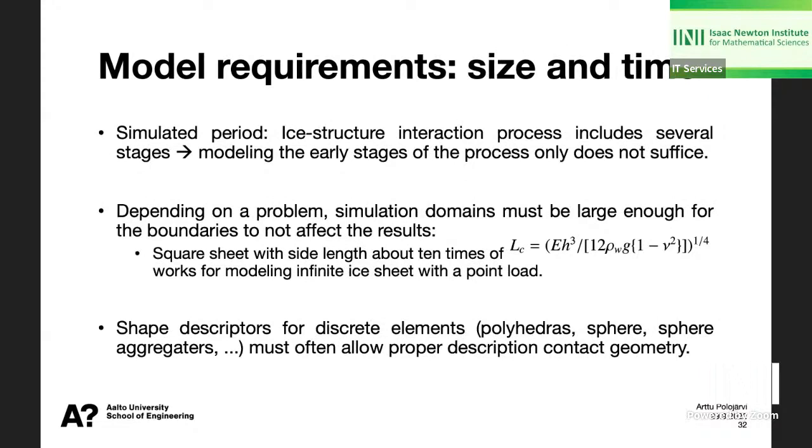Other requirements that I saw when doing this work: like I mentioned, it's not enough to just model the first few meters of ice-structure interaction or the first few seconds, you in fact need to model long periods of time. And something I did not mention, but has been known since the 90s at least, is that you cannot model these situations using spheres or circular elements, because then the interaction process itself changes and the pile-ups change.